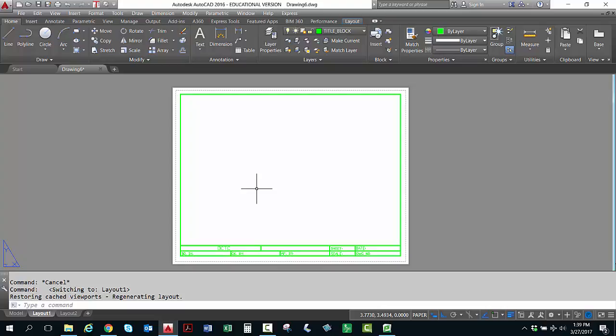In the Dimension Style Manager, set your options under the Fit tab to control the appearance of radius and diameter. Now, you don't want to dimension it. I wouldn't recommend dimensioning it until you get your viewport set. So go to page 724, and we're going to create a viewport in there.